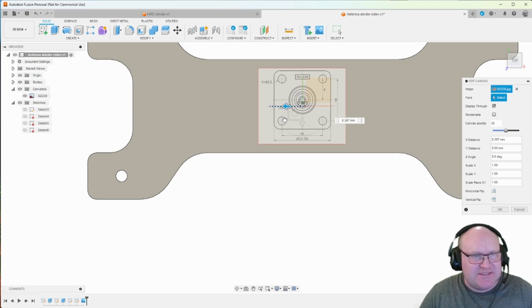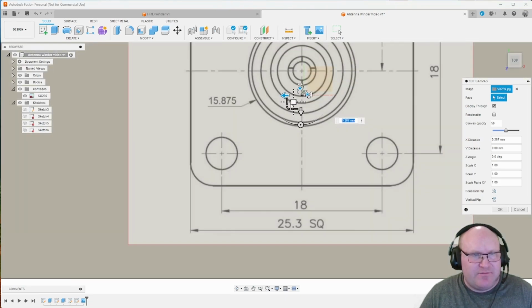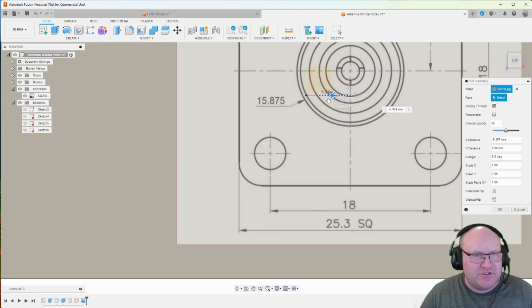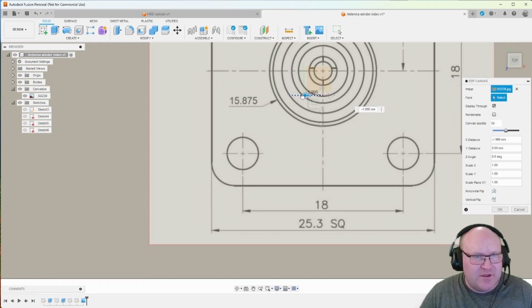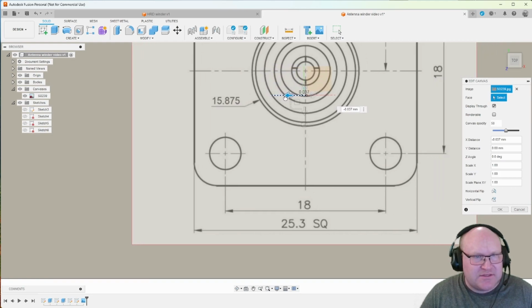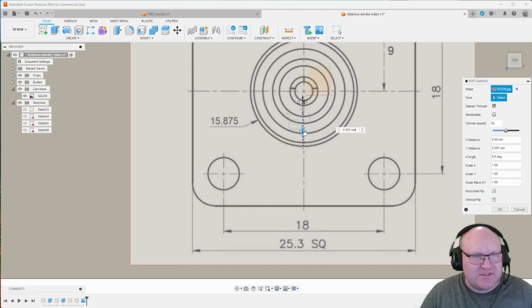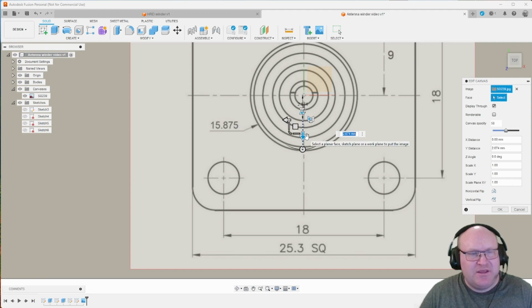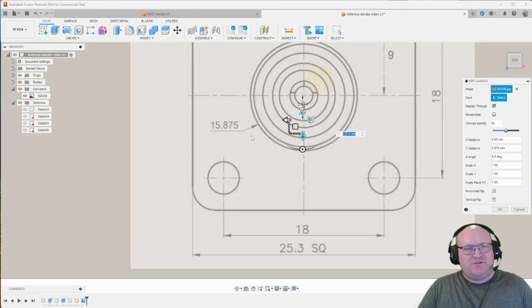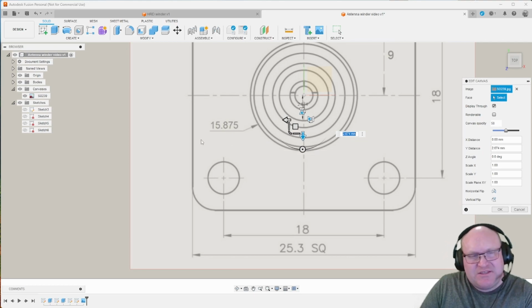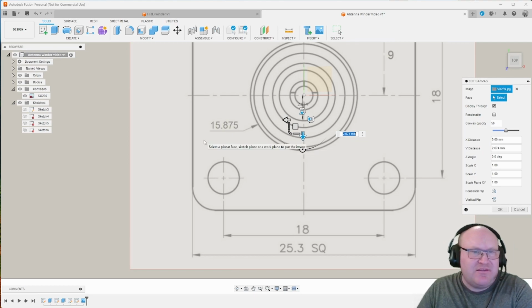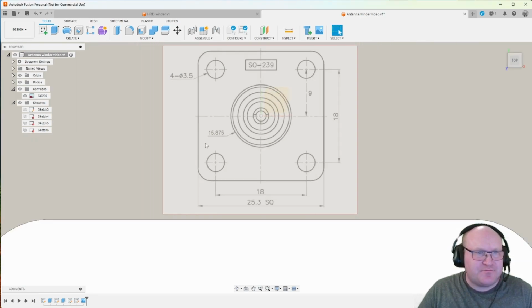This isn't an exact dimension, but it's going to be close enough for most purposes. And you can see here the origin point is kind of hard to hit, but if I drag it here, and say you have the green line in the center up here, and then we drag it down so that the center also goes directly in origin. This is going to be very close to the center of your model and more than good enough for you to draw off. Remember, this is just a background drawing. You're not getting direct dimensions from it. Press enter or OK to save that.